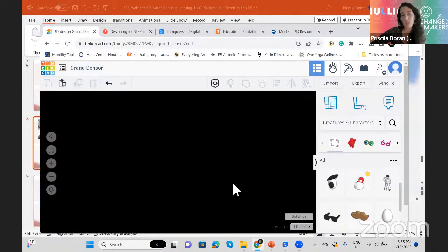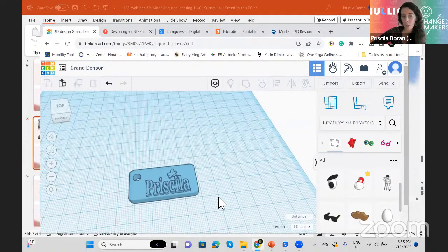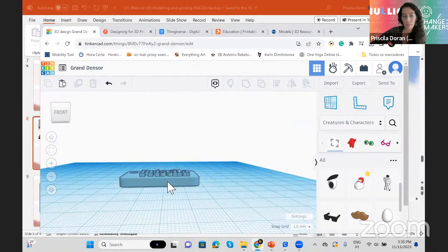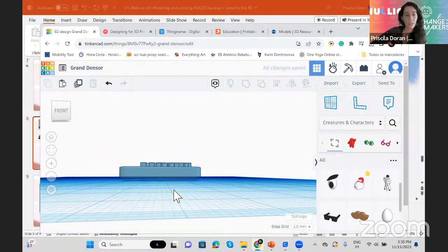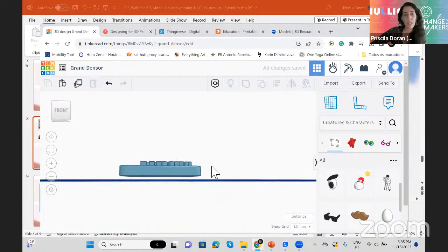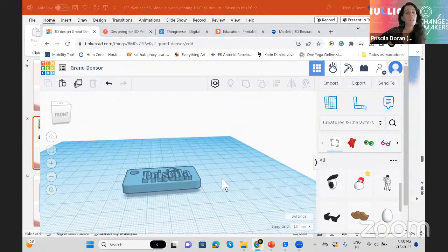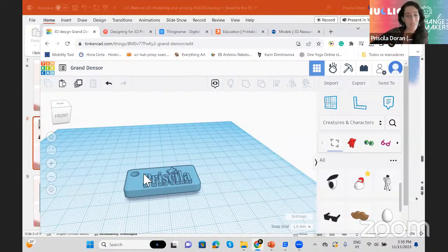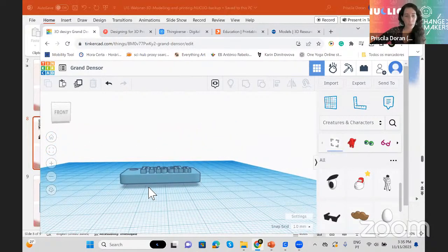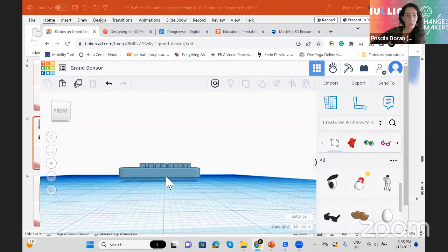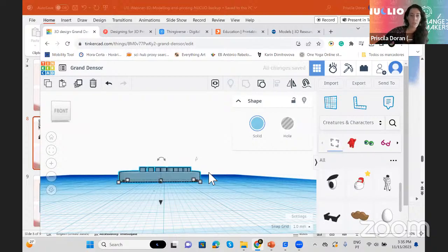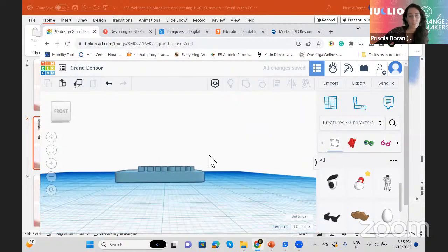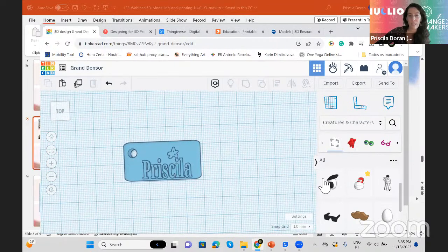These are things important to consider. One of the main things that we see students and even teachers doing is this. Sending something to print like this. And you see, this is not touching the ground. And many times we have, can you guess? Spaghetti. Because there's nothing to support the printing. So it is very easy. On Tinkercad, if you want it to touch the ground, just select it and click on D, and it touches the ground. And always make sure that everything is okay.